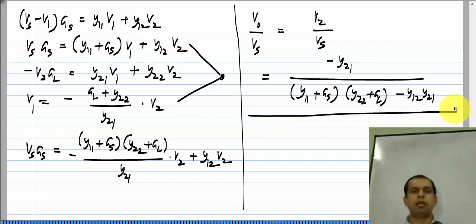Okay. So, you can take the model of the circuit, model of the 2 port in terms of the 2 port parameters, and analyze the whole circuit. Okay. We do not need to look at the insides of the circuit, that is the advantage. Okay. And of course, the 2 port parameters could be Z, G or H instead of Y. Okay. In this case, I took Y as an example, but it could be described by any other set of parameters. You can do the calculations in that particular set of parameters, or you can convert them into one of the other sets if that happens to be more convenient. Okay. So, this is one of the kind of calculations that you could do.